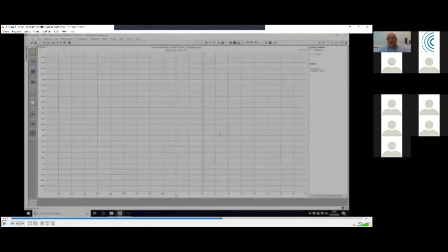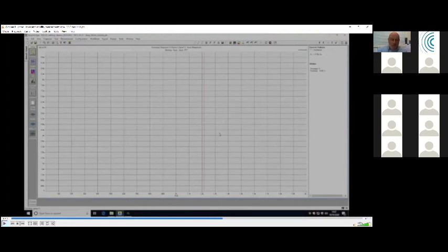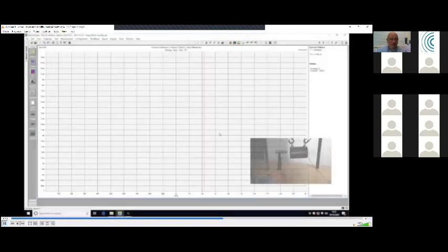Now, in Josh's excellent presentation, he mentioned the term mobility. And so what we're measuring at the moment is a thing called accelerance, which is the acceleration over the force, but mobility is what we're really interested in. And that is the velocity over the force. And so what we ask the analyzer to do is to integrate the acceleration channel. And if we do that, we should get the mobility of the block. So let's have a look at that result now. Again, we're averaging.